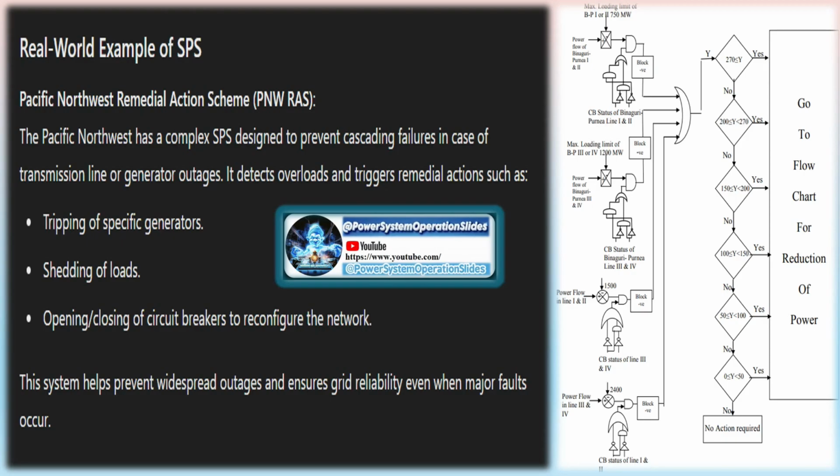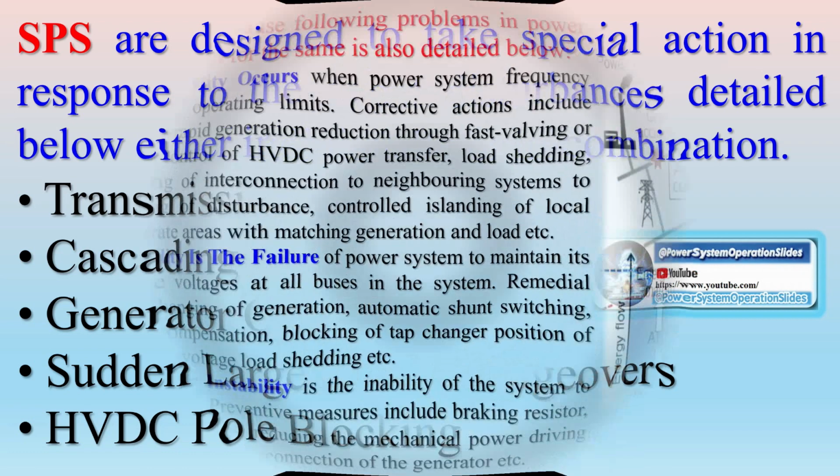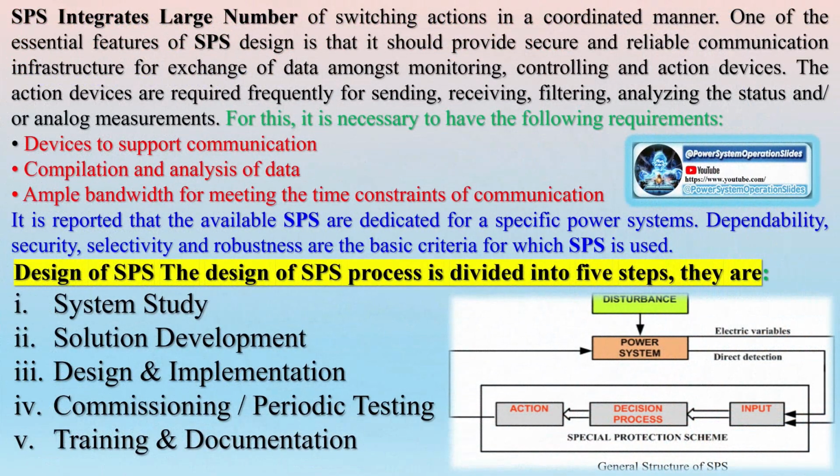In certain cases, SPSs can be designed for the detection of system conditions which result in overloading or voltage collapse leading to instability. This may require disconnection of single or multiple lines, generator tripping, increased HVDC power transfer capability, premeditated load shedding, or other actions which may cause problems of concern. SPS initiates corrective actions in mitigating the consequences of abnormal conditions without involving the isolation of faulted elements. SPS are primarily used where protection is employed on the capability of the power system instead of specific equipment protection.